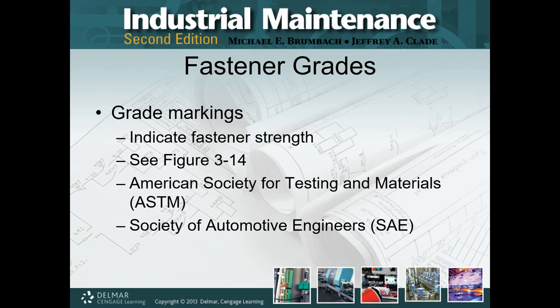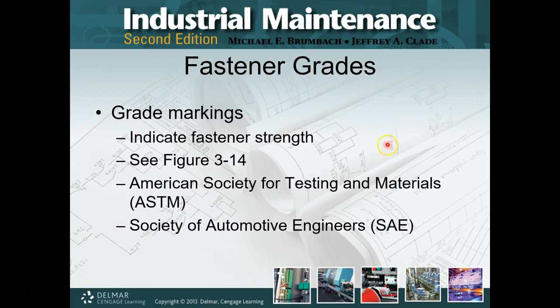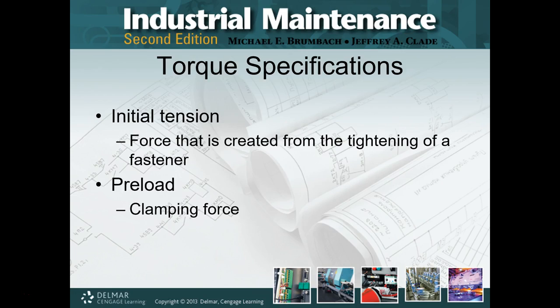I do have a little bit on the web page for it, or the Canvas page. In case you're wondering, it is the American Society for Testing and Materials that does the grade markings, as well as the Society of Automotive Engineers. Yes, the Society of Automotive Engineers does a lot of our bolts, because there's a lot of bolts that go into a car, specifically a car's engine. So that information is now shared throughout the rest of the industry, and we get to use it as well, which is pretty nice if you ask me. And real quick, you'll find the markings once again on the heads of your bolts, and even on the sides of some of the screws.